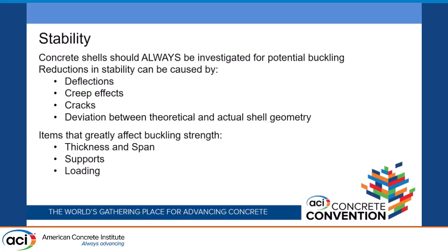That's where we get lots of bending, and so we need to be aware of that. But if we put a big point load on a shell, that is not accounted for in our membrane solution. So we have to understand that a big point load is going to introduce big moments into parts of the shell that were never really designed for moments. And so we have to figure out how to resolve those.